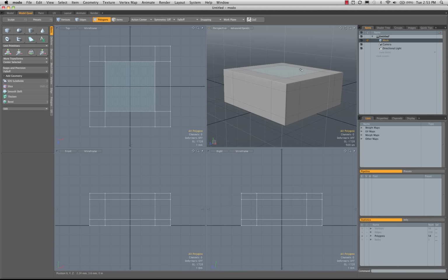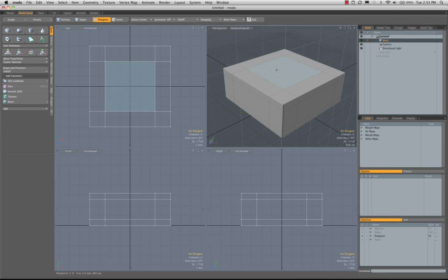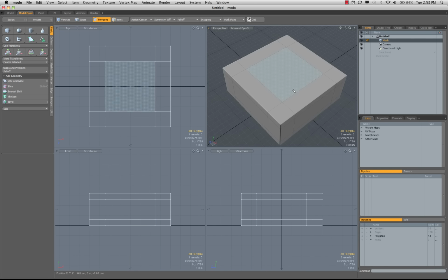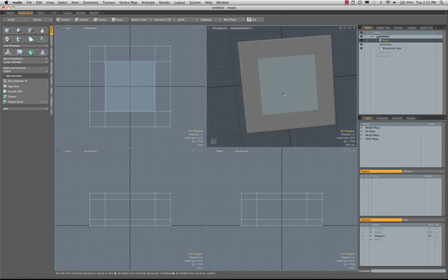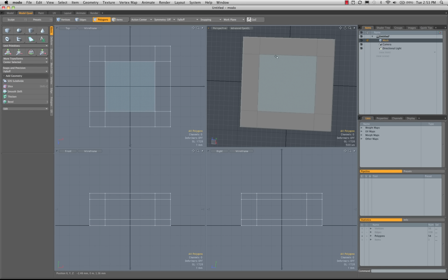Okay, so there's the general shape here. Now we need this circular piece in the middle. And the size of this is, well, we have a 1.6 millimeter gap on either side. So that's going to give us a total of 3.2 millimeters coming across here. So our diameter here is going to be 4.8 millimeters.